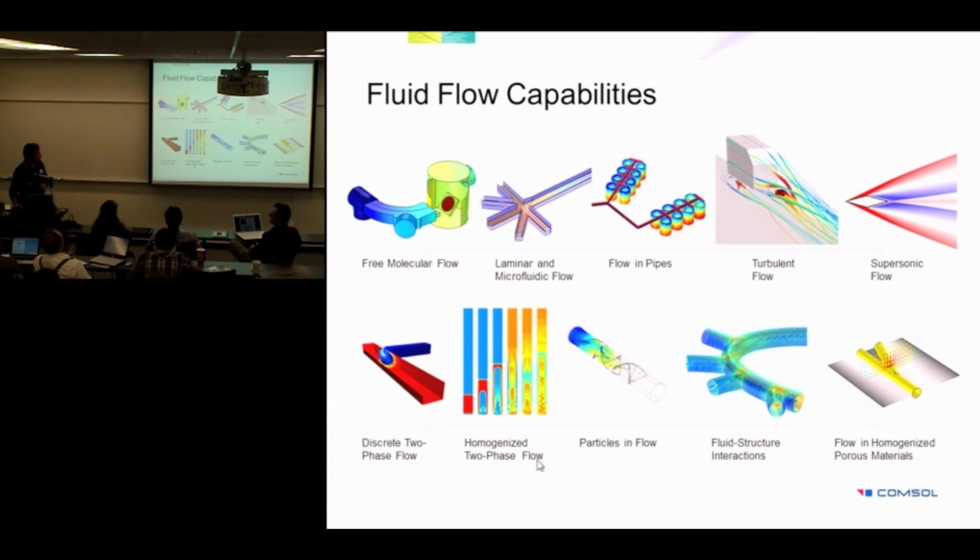We also have a homogenized 2-phase flow if you are assuming that your solid particles are mixed in some liquids and your solid is assumed to be in a continuum of certain volume. So you could use basically an Euler-Euler approximation for these kind of systems where you have 2-phase flow. And homogenized 2-phase flow like the Euler-Euler model are basically found in the CFD module instead of microfluidics.